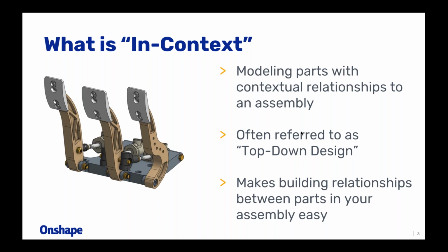Especially if you're designing configurable designs or anything along those lines, building relationships between parts makes updating them very easy. You can control a whole bunch of parts with a single dimension or a couple of dimensions or features and make a really powerful CAD model that updates very quickly. So it's a technique that takes some skill, but again, has big benefits.